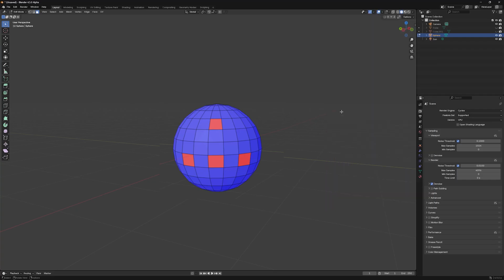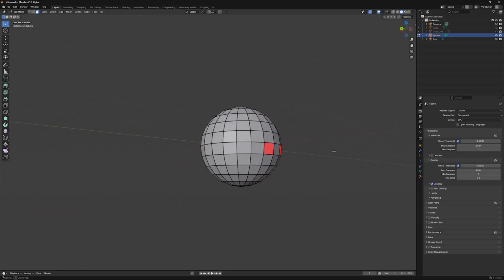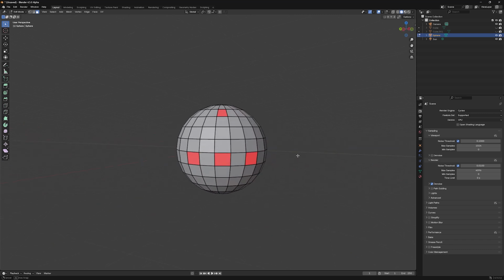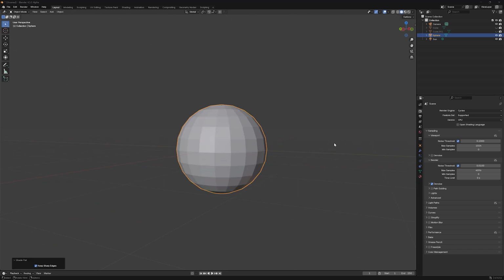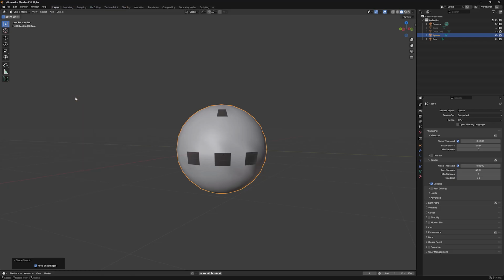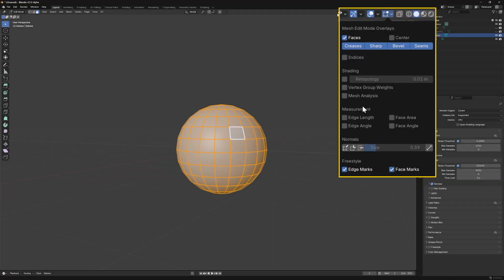In older versions of Blender, front-facing polygons showed in blue, but their color now remains unchanged. Visible back faces did, and still do, appear in red. The most obvious problem with a back face being visible is that the shading in that area of the mesh will be incorrect. We'll discuss the other two types of normals in the next video.